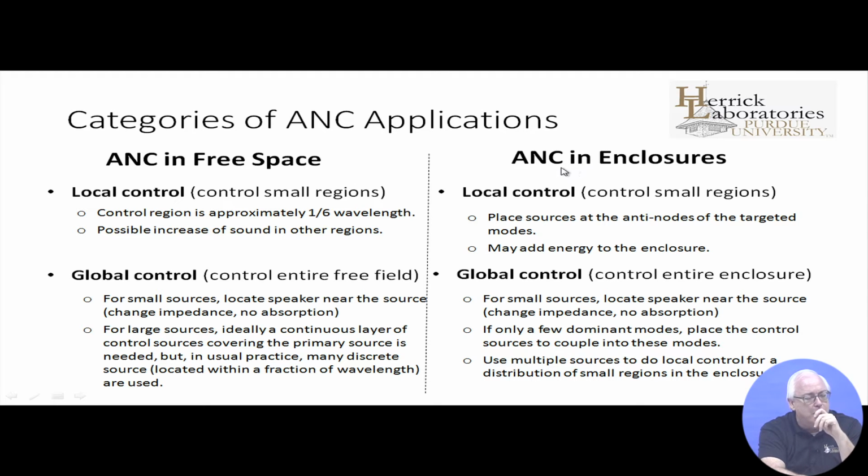On the other hand, we have active noise control in enclosures, in confined spaces like rooms or automotive interiors or aircraft interiors. And in each instance, we have a choice between local control, where you're just trying to control a sound field at a particular location, or global control, where you are trying to control a sound field in the whole region, so everywhere.